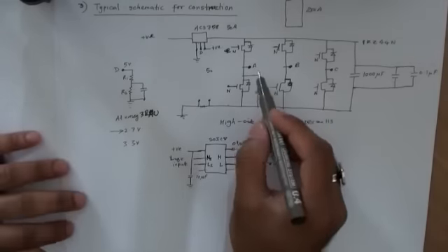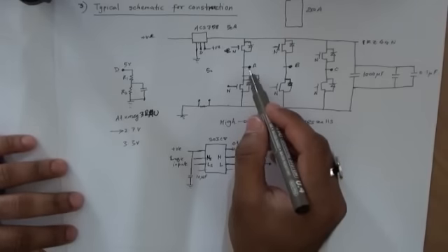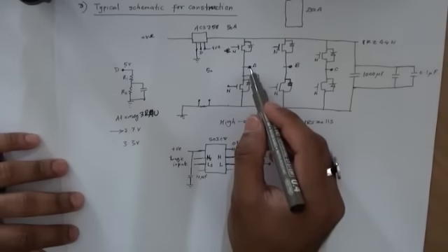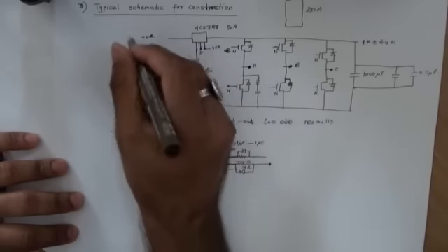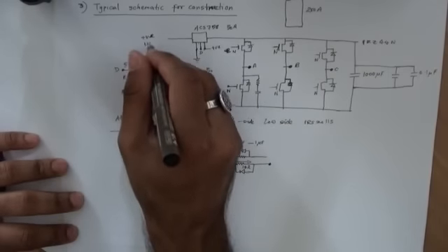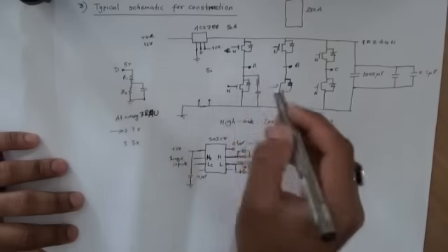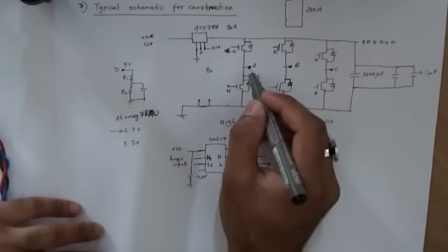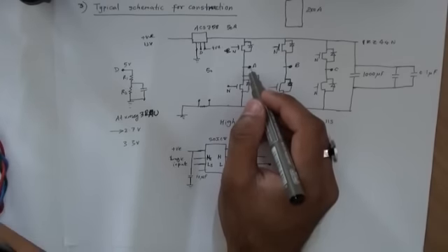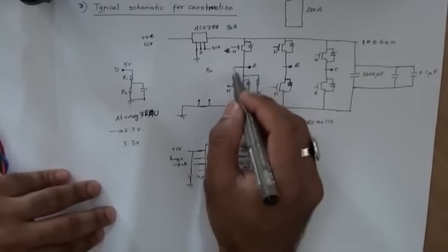So to look at these back EMF values, you could potentially be reading up to the supply rail. So for example, if you were supplying this with a 12 volt supply, you could potentially be getting up to 12 volt being read across here to ground.